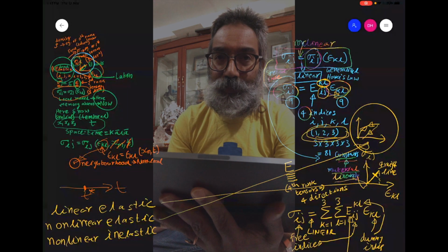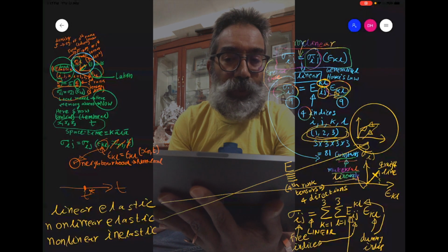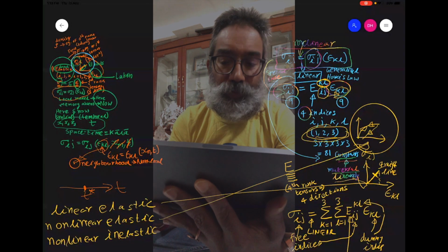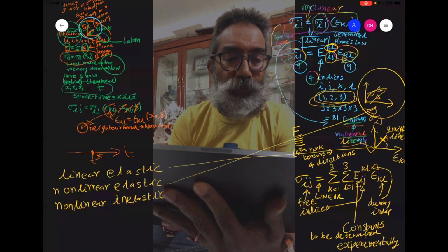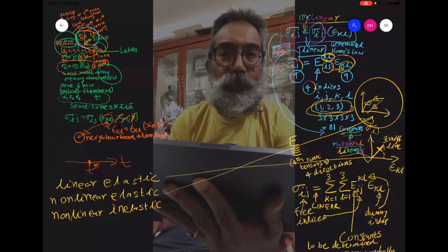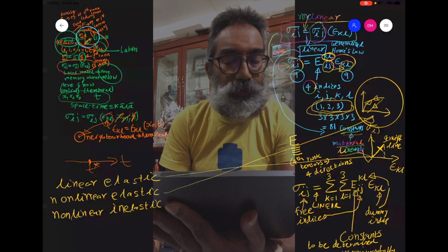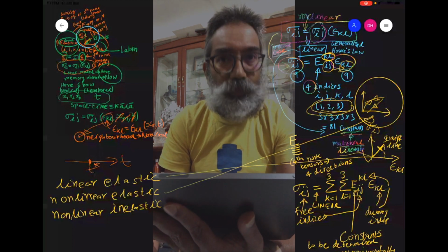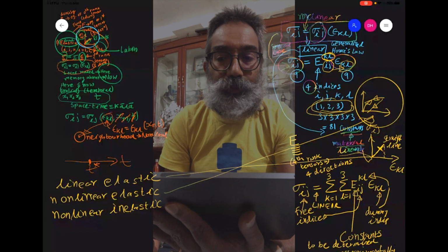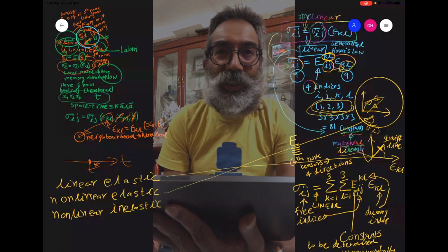Any other questions? Sir, yeah. So, in the elastic material assumption, we assume that the stress at a point depends only on the strain. Correct. The thing that I want to know is the direction of the strain, does it matter? Like, for example, does sigma 11 depend only on epsilon 11, or does it depend on all the epsilon kl? Yeah, good question.